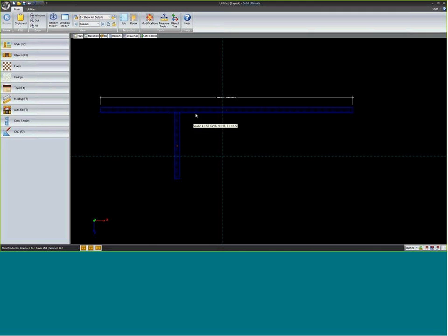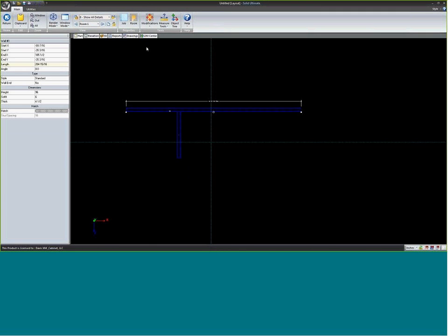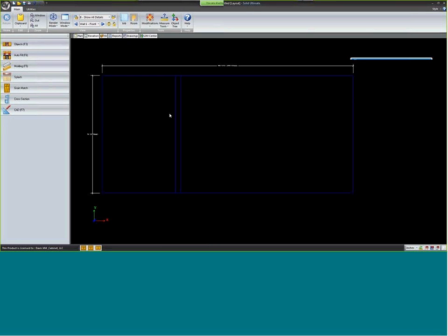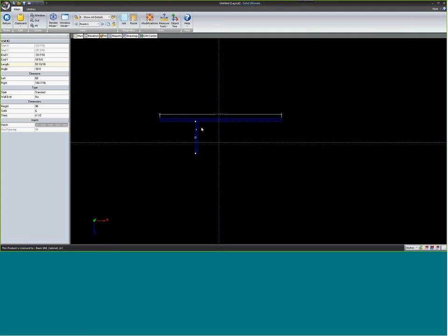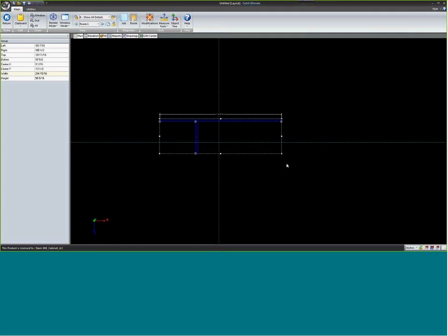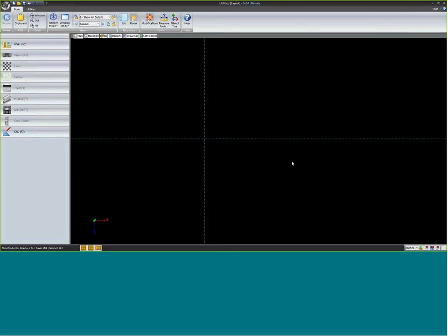The nice thing about doing this is that now if I go to the elevation view of this wall, I can see the T-wall plus I see the cabinets that are attached to both walls, rather than if this were drawing as a wall, and then this is a separate wall. Walls are really handy. I'll delete those.